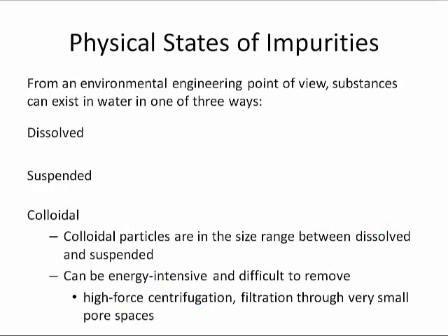The third physical state that impurities are present is colloidal. Colloidal particles are in the size range between dissolved and suspended. These are extremely stable suspensions. You will know of a colloidal system as salad dressing or mayonnaise. So it is extremely difficult to remove colloidal particles. It can be energy intensive.